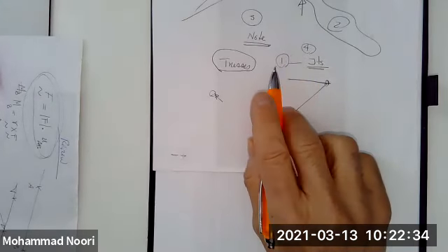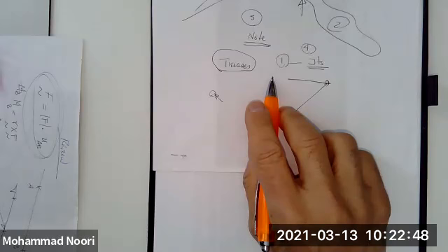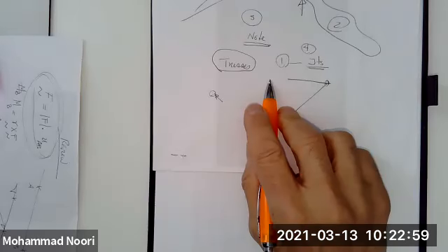So you cut that member and no more than two other members, otherwise you end up with four unknowns. The truss is cut into two pieces. Consider the equilibrium of either of those two pieces and find the unknown member that you've been asked to find.